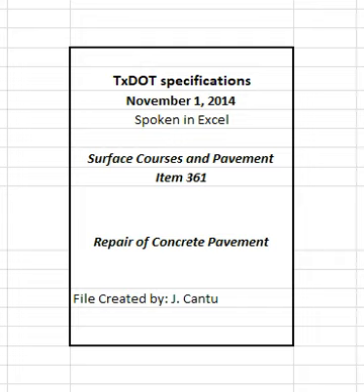Saw cut and remove additional concrete as directed, after slab removal, if distresses are found in the surrounding concrete pavement. Repair damages to concrete pavement caused by the contractor's operation without additional compensation. Perform repairs as directed. Remove loose or damaged base material completely, leaving no loose base material.